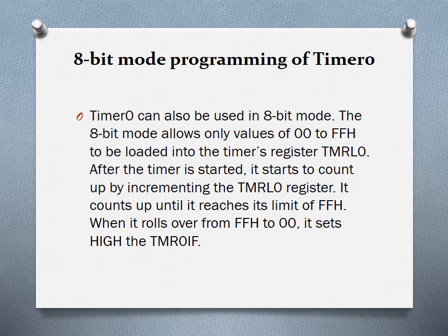So one register is the timer register low and the timer register high. These are the registers which will hold the value for a particular delay. I'll teach you the calculations later. So these registers should be loaded with a value that is needed based on the specification.